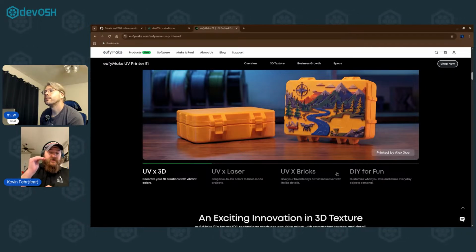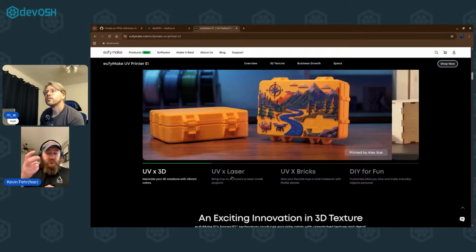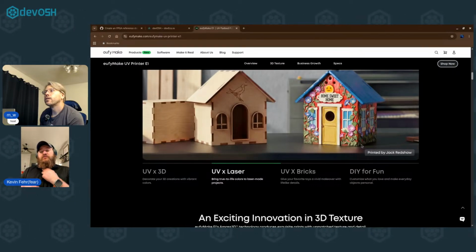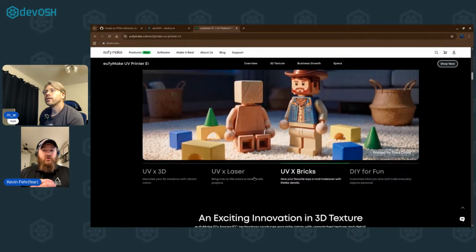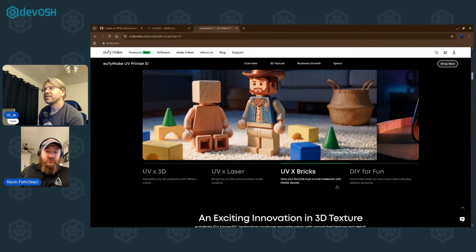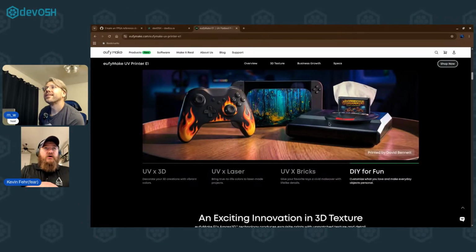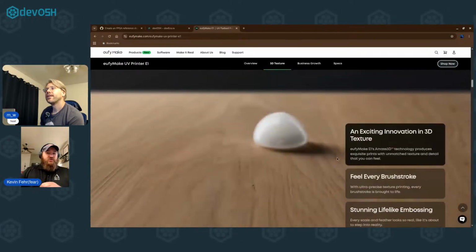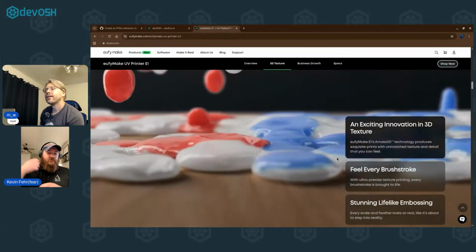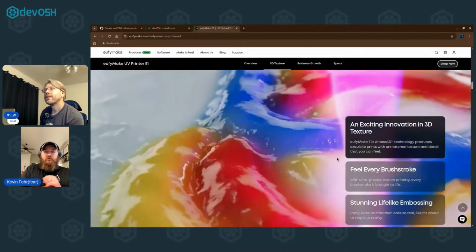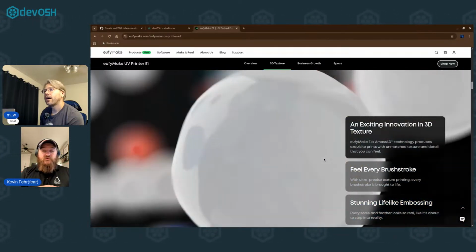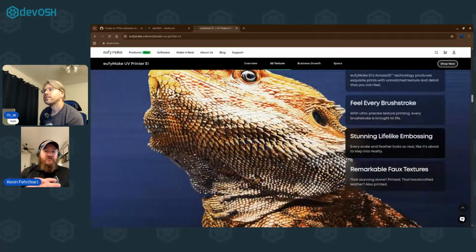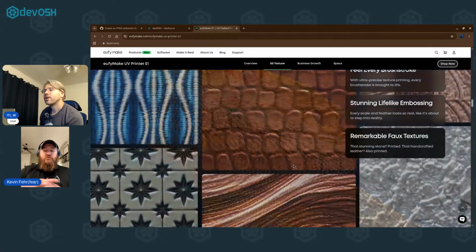And that seemed to make a big improvement. So with those two combined, I think I might not have to do any additional step for getting the UV to stick on there for a lot longer than before. And then the final option was I brought some clear coat acrylic enamel with me, and I just did a couple coats with the spray paint enamel, and it seemed to do the trick. So those are the three near-term, low-cost alternatives to improve the overall durability of it.